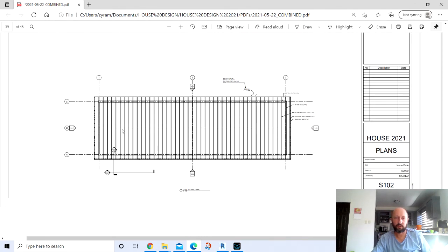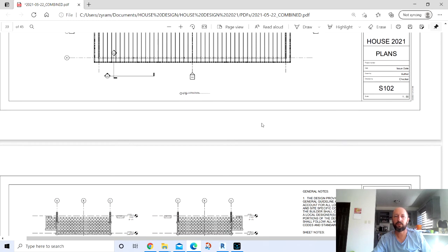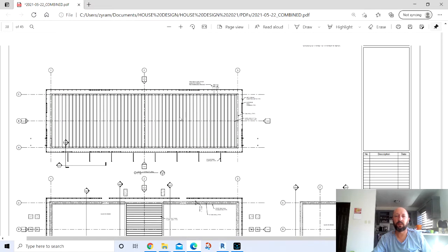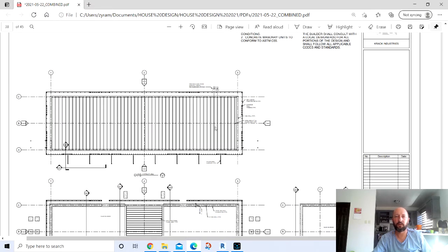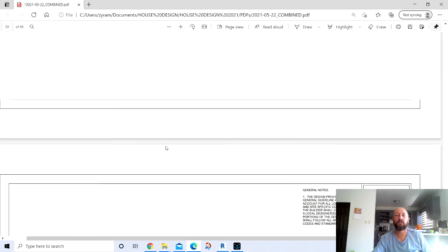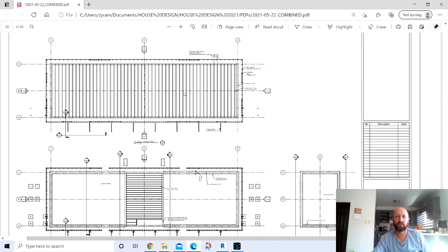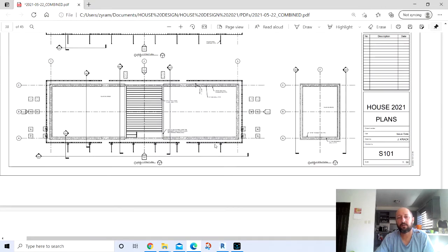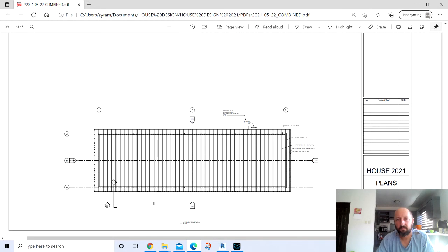And then the roof structure is engineered I-beams setting on top of your CMU structure. And depending on your manufacturer's recommendations, I think we got 12-inch spacing for the engineered trusses, 16-inch spacing for the engineered trusses, and 18-inch spacing for the engineered trusses, and 2-foot spacing for the engineered I-beams.